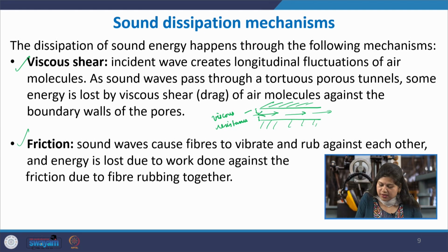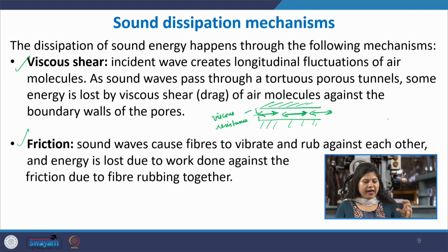And here the air particles are longitudinal oscillations flowing back and forth through these various air channels like this. Because you have numerous such small channels, the viscous resistance becomes important and dominant. In the same way, when the sound waves are moving through the structure, they can cause the solid structure or the fibers to vibrate and rub against each other, and some of the energy can also be lost due to the friction of the fibers rubbing against one another.